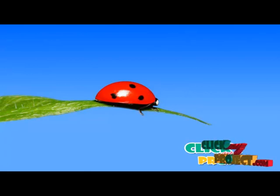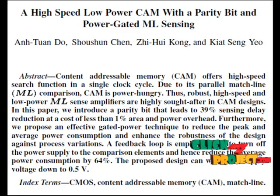Here I am going to discuss a high-speed low-power CAM with a parity bit and power-gated ML sensing. Most memory devices store and retrieve data by addressing a specific memory location. As a result, this path often becomes the limiting factor of systems that rely on fast memory access. The time required to access an item in memory can be reduced considerably if the item can be identified by its content rather than by its address. A memory that is accessed in this way is called content addressable memory, or CAM.